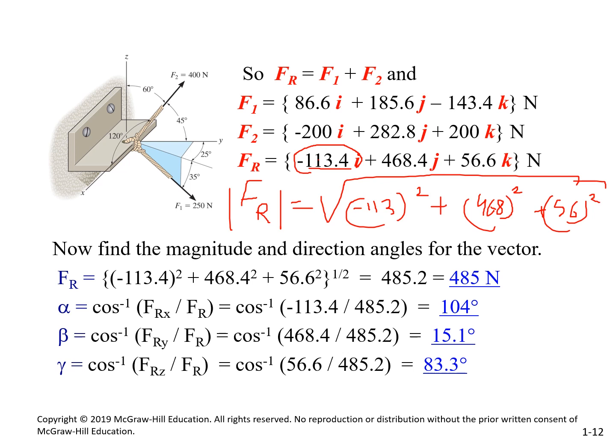Take the x component divided by the magnitude that we have as 485. Take the cosine inverse. Those are your angles. So now I know the resultant and the angles, the direction of it. That's a quick refresher about how we do the resultant force and what kind of angles, because the angles are important. We have projection angles, we have coordinate angles.